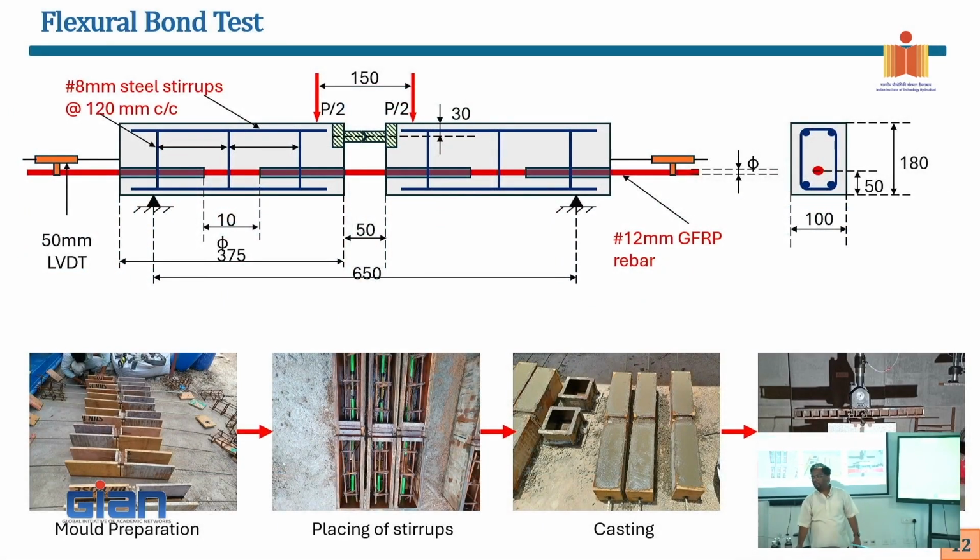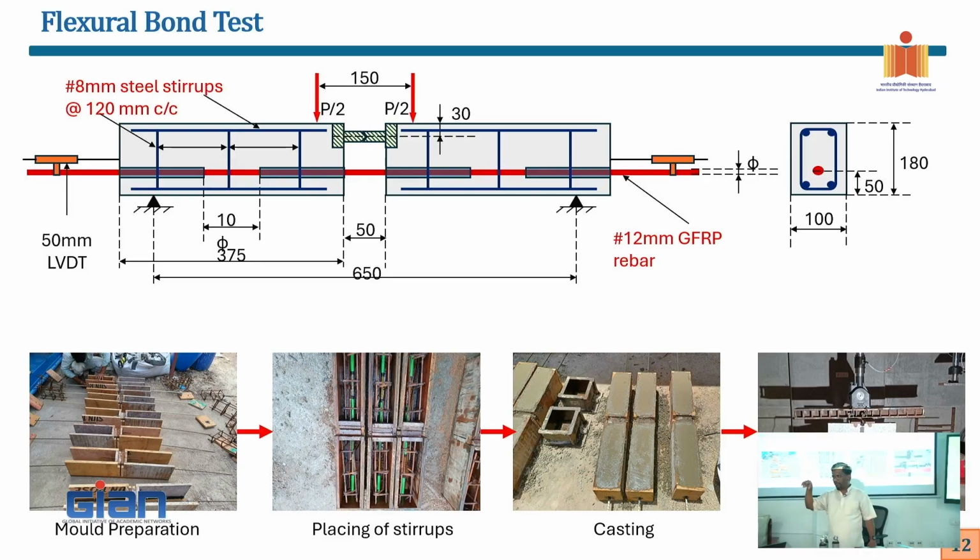I have one doubt, sir. Because when we calculate the I cracked, we use the tensile strength of the concrete. No, for I cracked, we don't do that. MCR, when you do the calculations, is just at the incipient of cracking, just before the concrete is going to crack, you calculate the moment by using the stress. Okay? This ICR is not corresponding to that MCR.